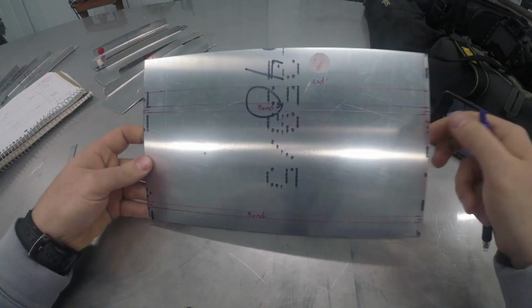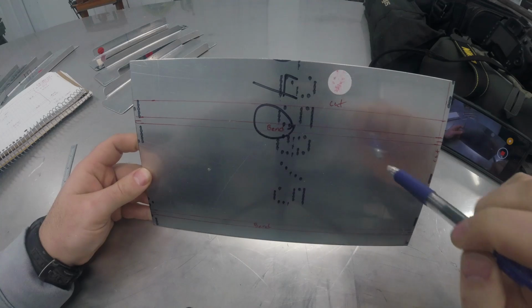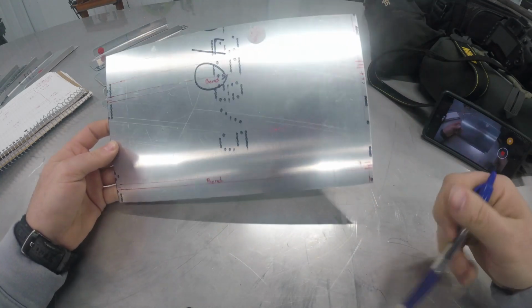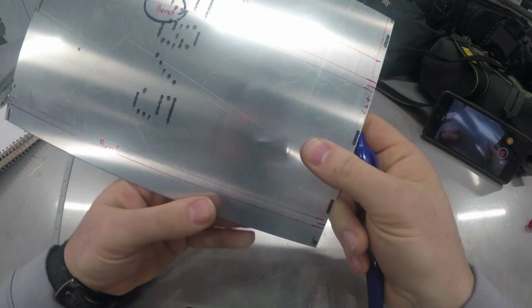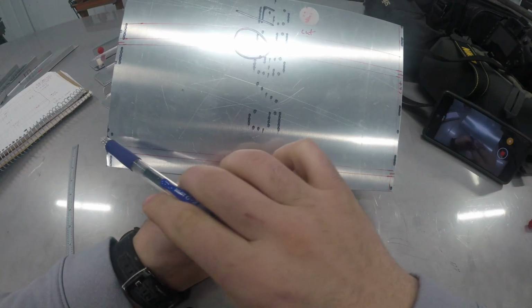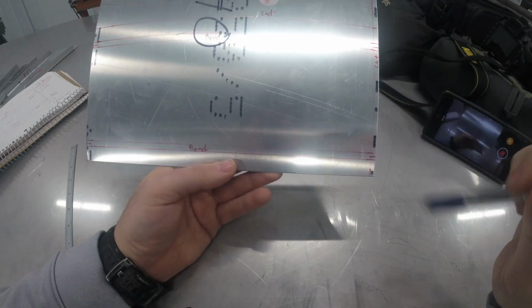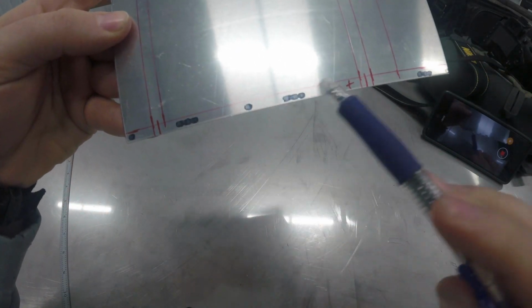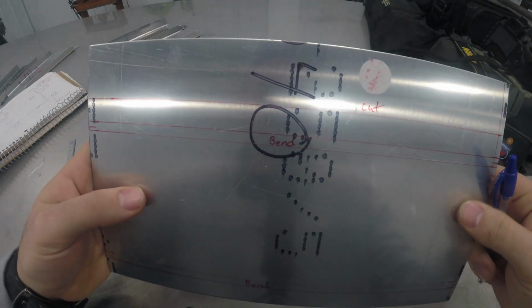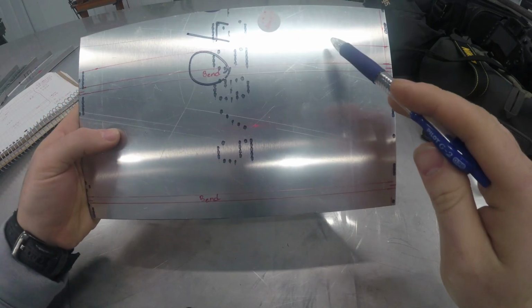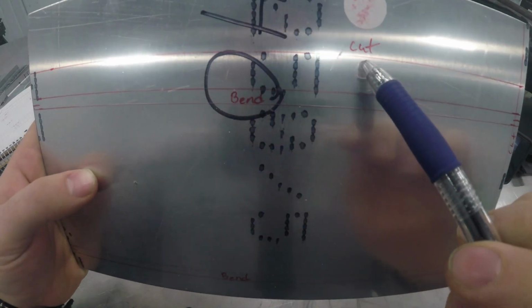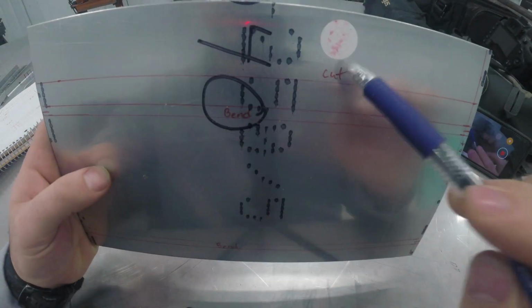So then we can go to our material that we're cutting here, and the video cut off, so I actually have to remake this, but I've got everything marked out now. So basically just measured from one end to one end because we want 11 inches. So then you can see here I've got a line on the bottom side here, cut line, and then our overall length we want to be from here up 5.3 inches. So you can see I've got my cut line across the top here.